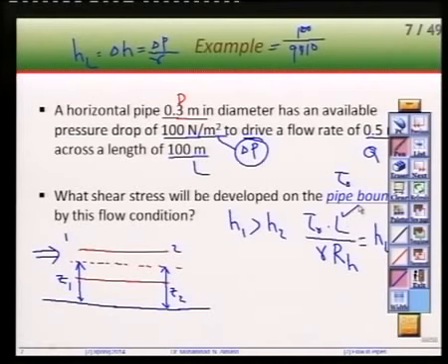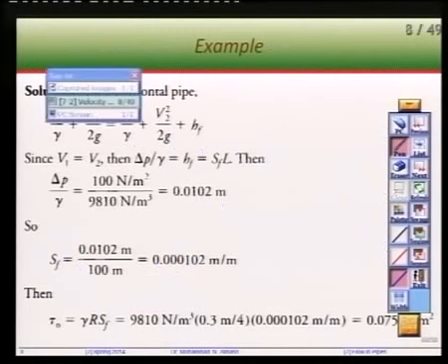The hydraulic radius, we said last time, D over 4. Now, I don't want anybody to go and say the area over the wetted perimeter. No, just immediately put it D over 4. And gamma, it's rho G. Or, as we already put it there, doesn't really matter, and that's it in the end. And so then you can find the boundary shear stress. You have the solution here.